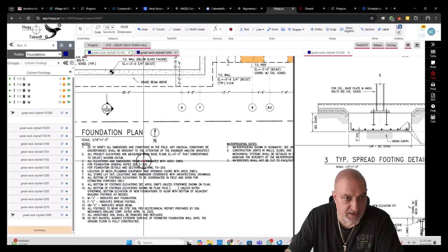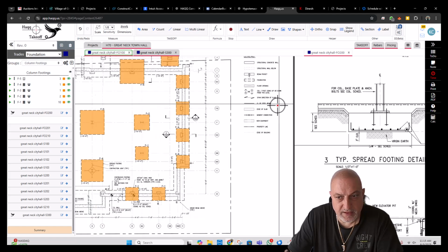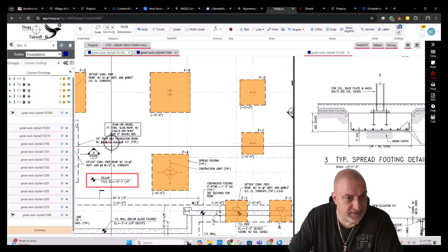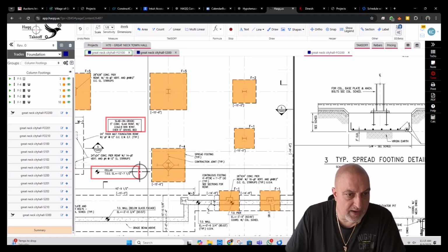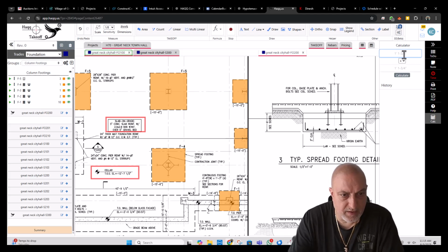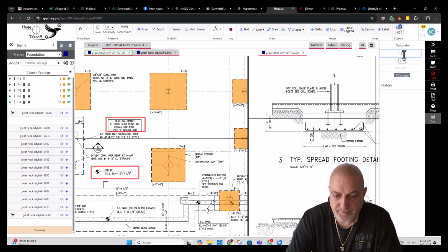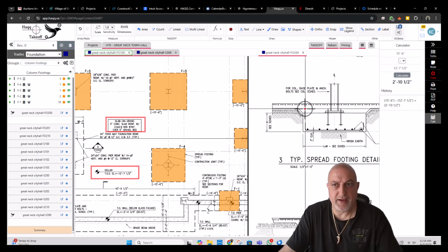What's the slab thickness? You think it's giving us? We are not that lucky. Hey, elevation is here, 5 inches. So we have minus 12 7.5. Let's see if this calculator works. Minus 15 foot 6 inches. It doesn't know minus. Okay, we say deduct from minus 12 feet 7.5 inch. Calculate. So 2 foot 10.5.